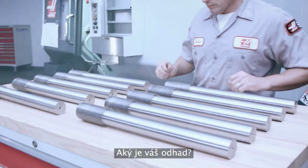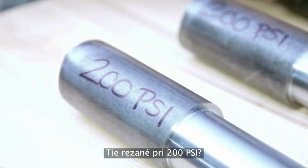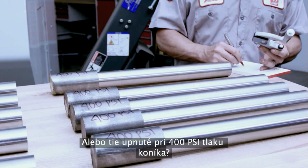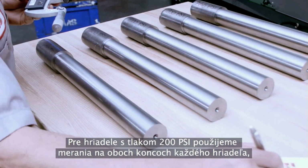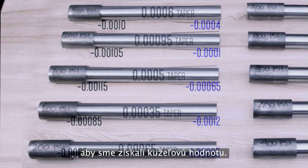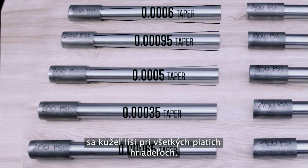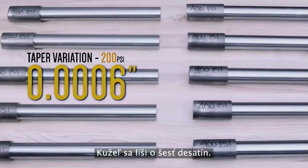What would be your guess? Which parts would have the best repeatability? The ones cut at 200 psi or the ones clamped at 400 psi tailstock pressure? Let's see. For the 200 psi shafts, we take measurements at both ends of each shaft to get a taper value. Then we compare these 5 values to find how much the taper varies for all 5 shafts. The taper varies by 6/10.